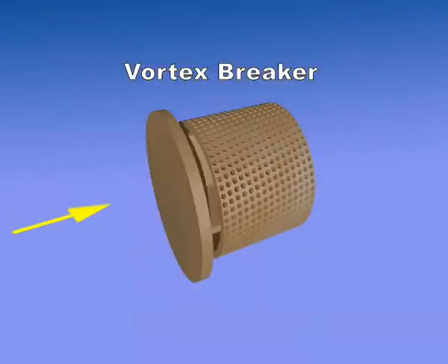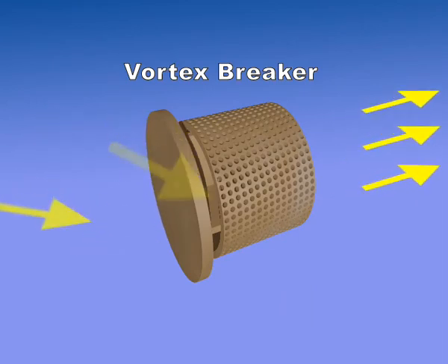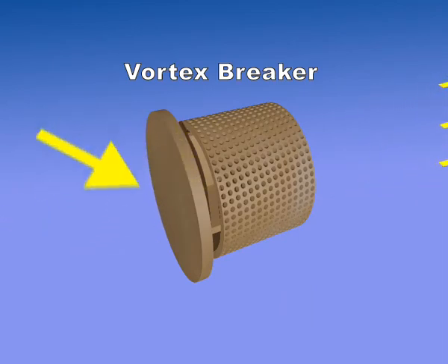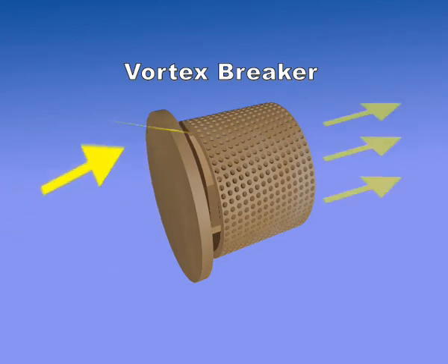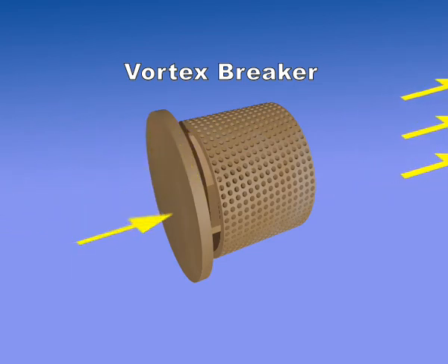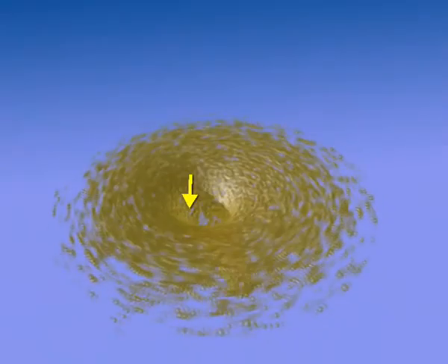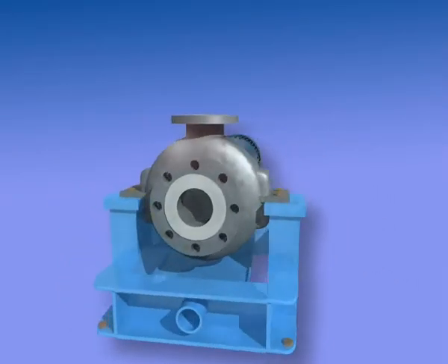Vortex breakers are devices that can be found at the liquid outlets. They are designed to eliminate gas carry-under in the liquid stream. The vortex breaker will stop the swirling of the liquid. A vortex-shaped swirl has the tendency to suck vapor into the liquid stream that could cause pumping problems.